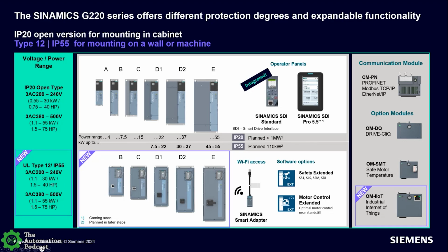We look at the software options, and I wanted to say a word about that. There are some basic safety functions built in. You alluded to that, that somebody might want to specify a drive because of some of the safety functions. As standard, there's a handful of safety features built in, such as safe torque off, which is pretty common. But then also there's a timed safe stop. And then you can see on the screen there the safe motor temperature module, which is applicable to motors used in ATEX environments. So good applications there in oil and gas, maybe, or chemical plants, where I have a motor in an ATEX environment. That device is ATEX rated.